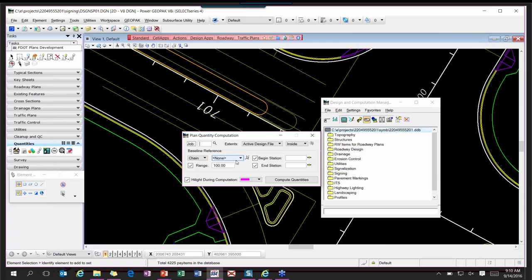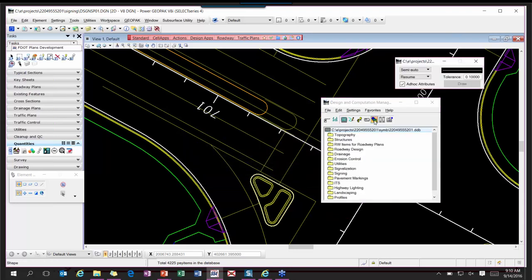We have the compute mode. The compute mode allows us to calculate our quantities, and we'll be looking at that more in a later chapter. Shape mode, there's only one pay item I can think of in pavement markings that you would even use this for, and that is the island nose paint. And I'm going to recommend that you don't use this, because if whoever's doing the roadway design is using the new features, which we hope they are, and the new civil tools, there's some intelligence behind the scenes, and elements that you see in the file, like this line, when it was placed as a civil cell, it sees that as being much bigger than what it is. So it can cause problems. So I recommend that you use the Create Region tool instead.